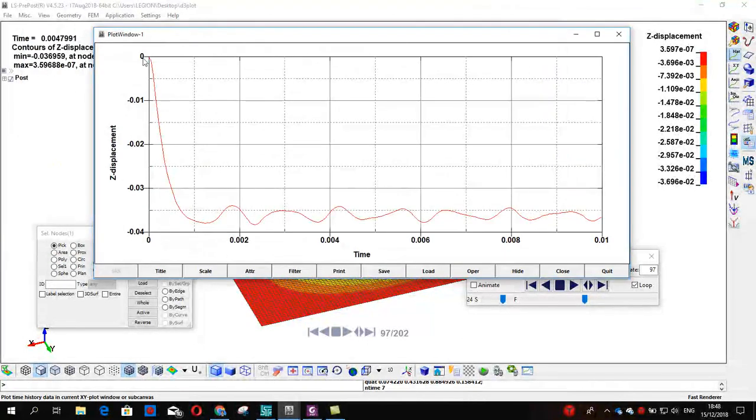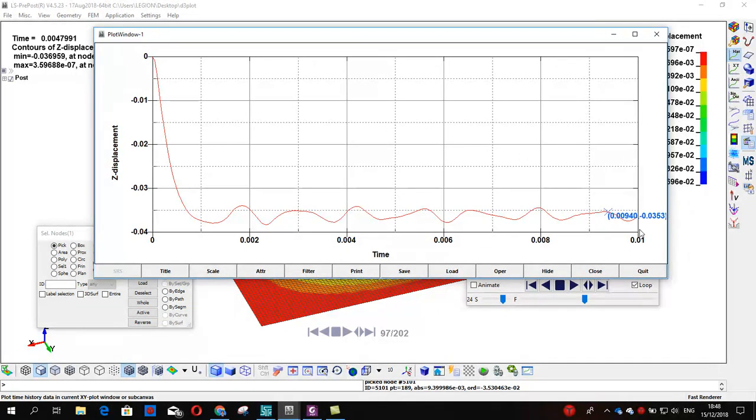Now you can see here the deformation of the blast wall, and this is 0.04 meter, meaning 40 millimeters, and the displacement is between 34 and 39, almost roughly among those values. So you can see here or here 35, and here is 37, and here is 34 again. You click here, this is 37.